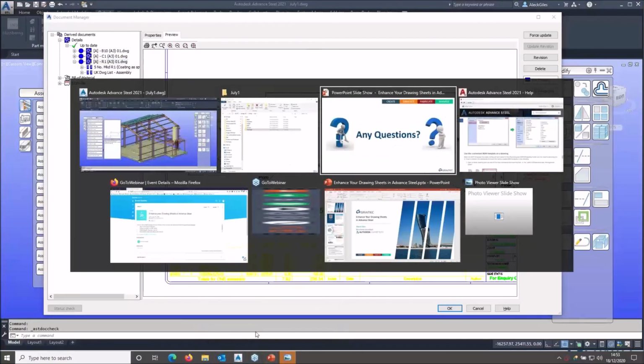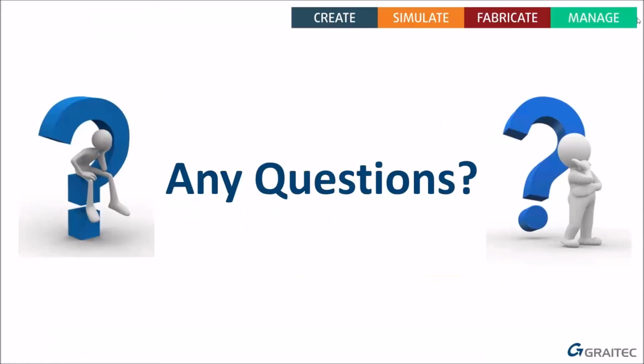Okay, let's have a look at your questions then. See, one or two have raised their hand. Okay, somebody's made a comment that if you're using an image, you can use paste special to paste an image into your title block. I'll take your word for it, Dave. I still prefer using plain AutoCAD elements because there's still a risk on printing that it sometimes comes out as a black rectangle. Probably not so much as it used to, but when you're printing black and white, it can be a bit ambiguous. Even if it's grayscale, which shade is black, which shade is white, because it usually draws a line somewhere between 60% is black, 40% is white, something like that.